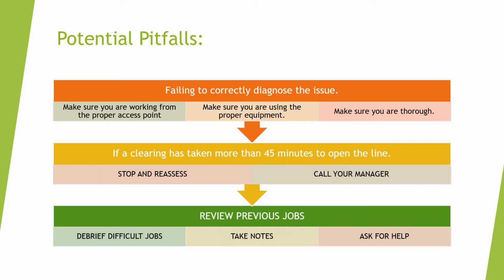Potential pitfalls. Failing to correctly diagnose the issue. Make sure you're working from the proper access point. Make sure you are using the proper equipment. Make sure you are thorough. If a clearing has taken more than 45 minutes to open the line, stop and reassess and call your manager. Review previous jobs. Debrief difficult jobs, take notes, and ask for help.